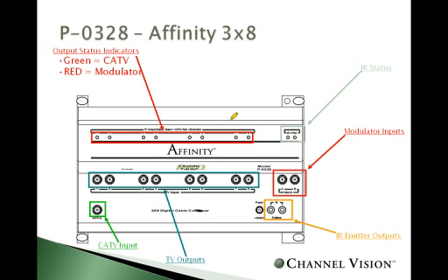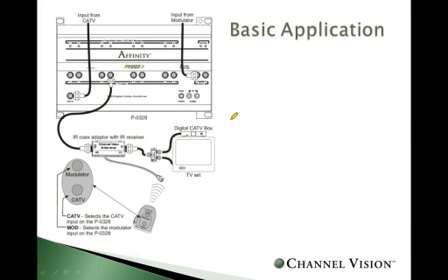So if I'm using this system, how's it going to be a part of my cable system? Think of this cable combiner as the 8-way splitter that your cable provider put in. Remove the splitter that your cable provider put in, and then this will essentially take the place of the 8-way splitter. Now you can utilize each TV leg as an individual television, up to 8 different rooms.